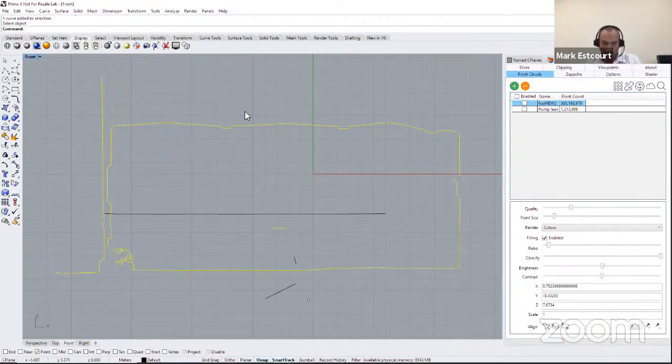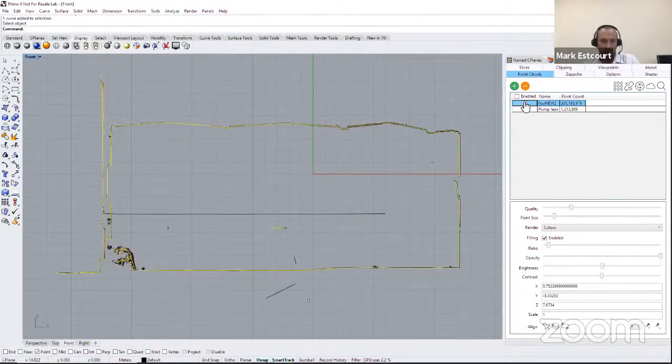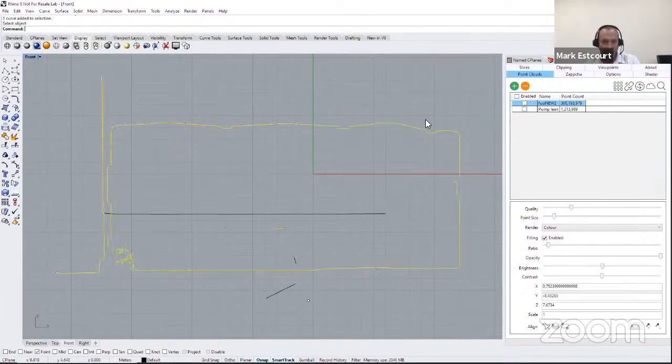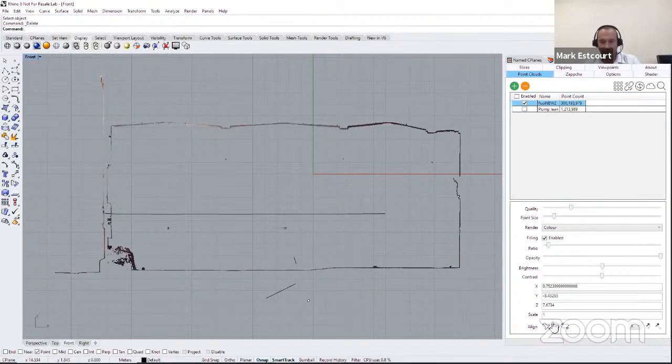He sliced through the building there, and he's clicked the vector feature, and it's automatically created the vector around those lines within the point cloud. So if we turn the point cloud off, you can then see that is a native polyline that you can then use or may choose not to use, depending on what the quality would be. But in this instance, it looks quite good.